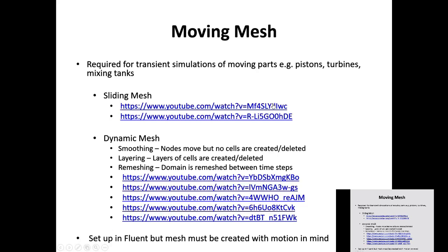There are two ways of accommodating this because it depends on time, doesn't it? There are two ways of accommodating the movement of the piston here. One is you can have grid nodes at a very, very high resolution, and you can keep on adding and removing layers from this volume.